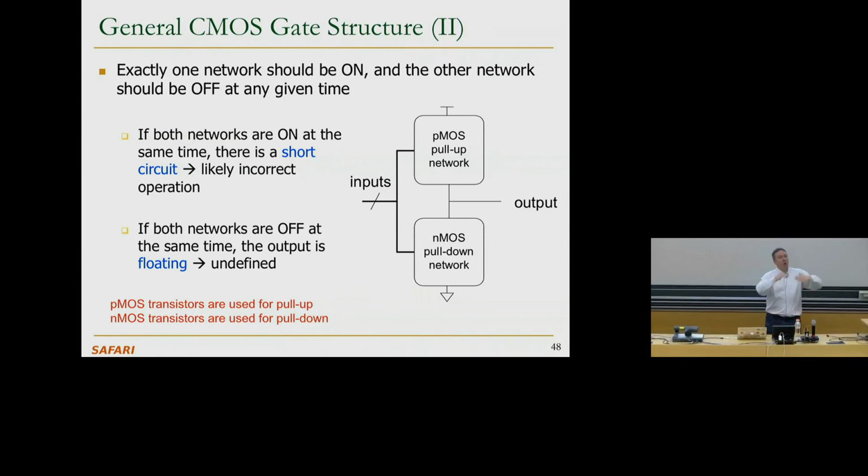We don't want both transistors pulling up and down at the same time. We also don't want to have the option where the output is not being actively driven.